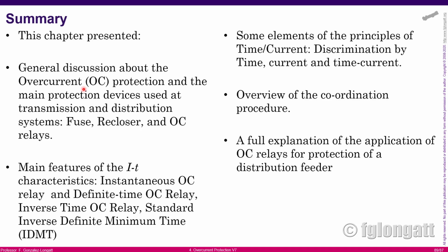Some elements of the principle of time current discrimination were presented, specifically discrimination by time and by overcurrent. We showed that discrimination by time alone has some drawbacks. Also, discrimination considering current alone has some problems, especially when the source impedance is changing.